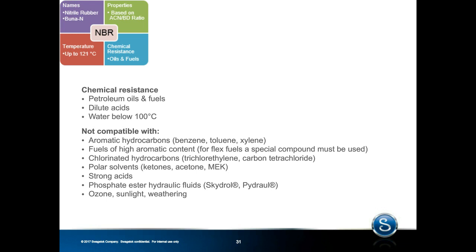If you remember not too long ago, I said that EPDM, or EP rubber, and nitrile sort of oppose each other. Look at what is considered not compatible for nitrile rubber. You have ozone, sunlight, and weathering, which, remember, were all very good for EP rubber.